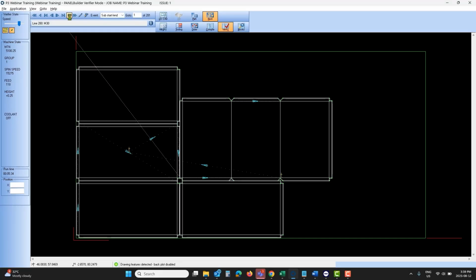And if you noticed, our changes were reflected immediately on verifier with the tooling that we have updated. The NC file would have been created from this within the nest, and you can see that within your project folder. From there, you can now send this to the machine for someone to go through and provide the actual cutting there.